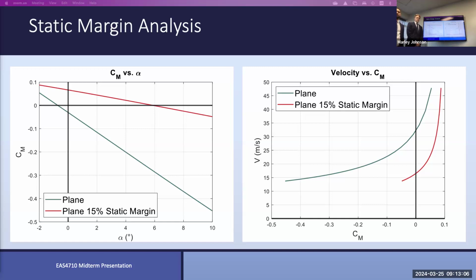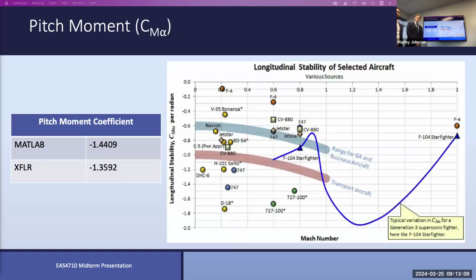Right. So saying to me, oh, I did MATLAB simulation, that's like saying, oh, I did Python simulation. That's the framework you did it in. What did you do? So essentially, I wrote code to use all of the equations in terms of stability. Obviously, the lift and the moment arms that the lift is acting from, essentially isolating longitudinal, lateral, and directional stability, and calculating those coefficients accordingly. This is one of the three slides, where we used the coefficient that I calculated in MATLAB using our textbook equations.